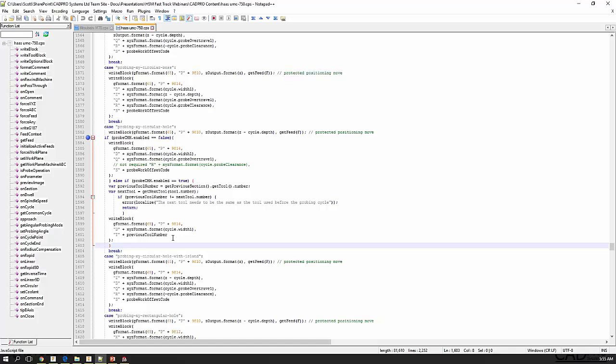So the only difference here between this cycle and the previous one is that we're still using the D value, but the function of the D value changes slightly, and then the T value, which is basically telling the control which tool or where offset to put the differential value into. Just keep a track on the time.